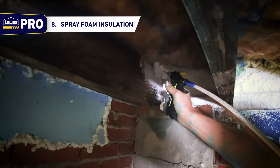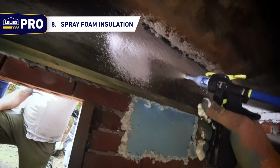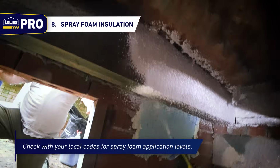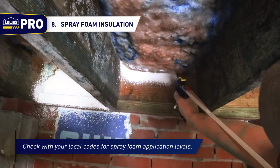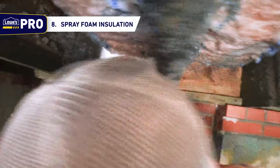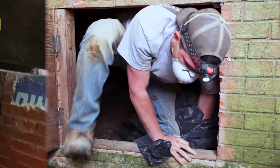Step 8. Spray foam insulation. Use a spray foam insulation in each band joist bay between floor joists and along the inside perimeter of the home. This creates a vapor barrier and increases the R value of the crawlspace insulation and helps keep the temperature outside from impacting the temperature inside of the crawlspace. Be sure to read all manufacturer's instructions before using. Use only as directed.